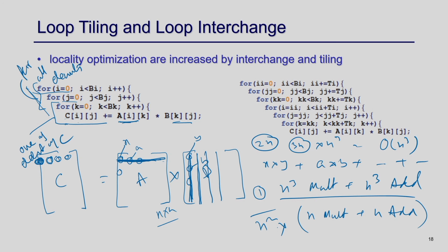But my objective, when I implement or realize a hardware for this kind of problem, should be that if a particular value is getting accessed many times, I try to minimize the access, so that I read it once and use it multiple times. That is the idea. So, the way I calculate this equation, my objective will be to reduce the memory access, so that the memory access time gets reduced.